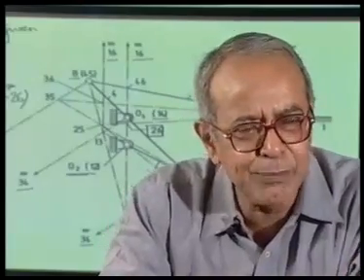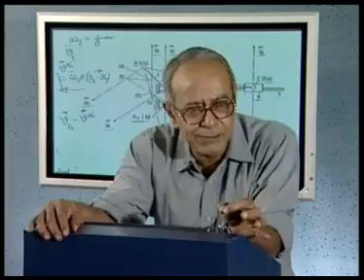For a 6-link mechanism, there are 15 relative instantaneous centers and all of them can be determined. Once we have determined all the relative instantaneous centers, I have also explained how we can use their locations for the purpose of velocity analysis. That is, given the input velocity, we can find the velocity characteristics of all other links present in the mechanism.